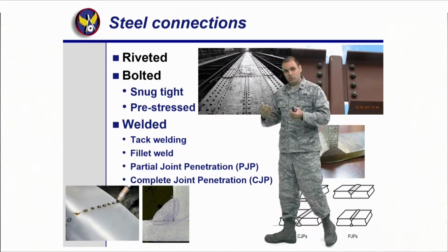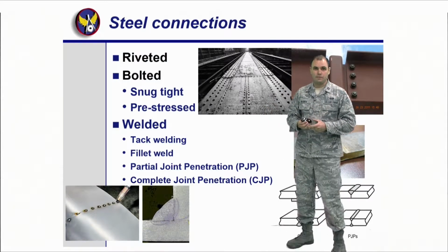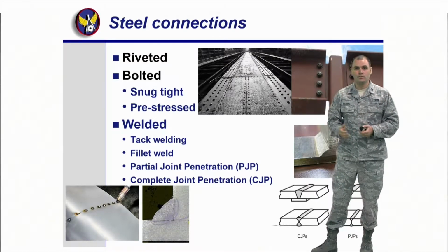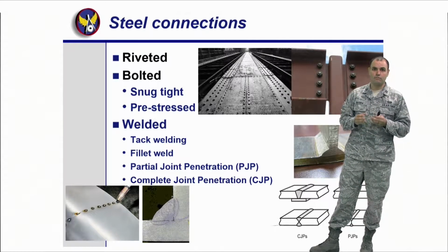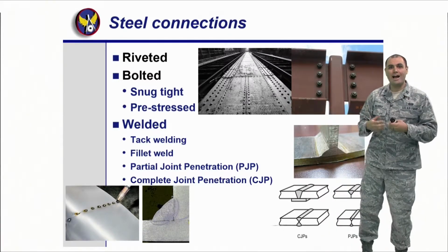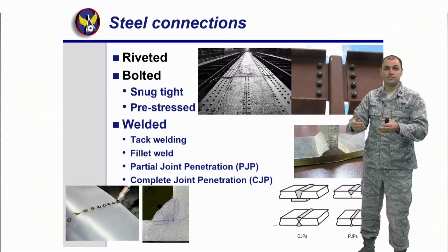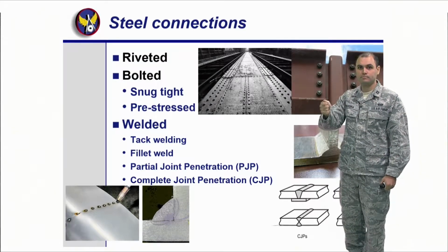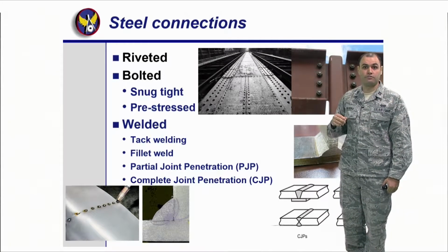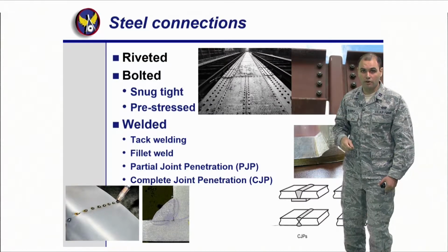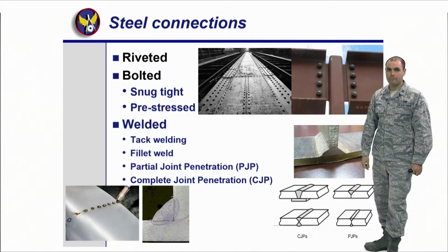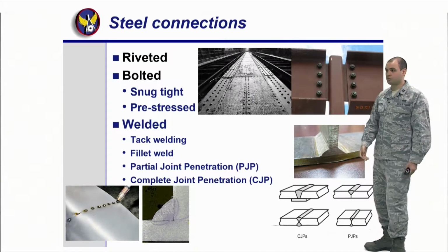And then weld it. Yes, you can weld. In the Air Force, I typically don't recommend welding unless you've got an experienced welder, because in the structural realm, they get certified for not just the type of welding, tack welding, fillet welding, partial or complete, but also how they're welding. What do I mean? Well, you can go to a class and get certified on how to weld standing up in a vertical line. But you also need to get certified if you lay down and do this. Or if you're hanging, right, you're 30 feet in the air welding, you need to be certified for that. Or if you're kneeling down in the bottom, each individual weld has a different certification, right? So again, because you're using welding as a structural member.